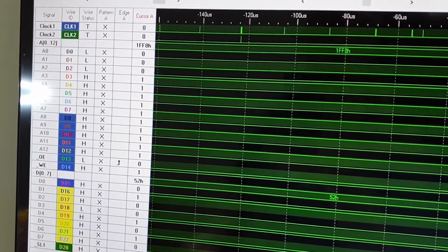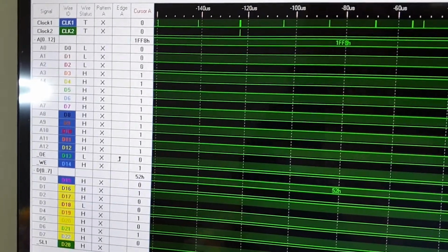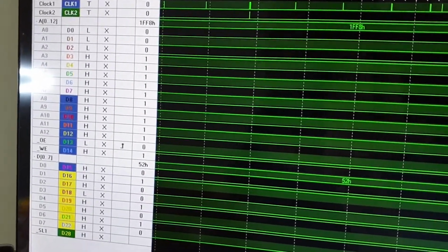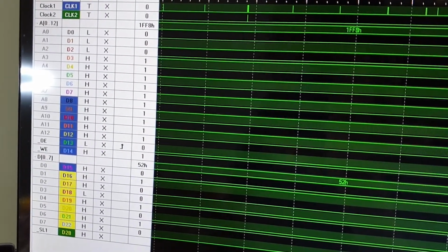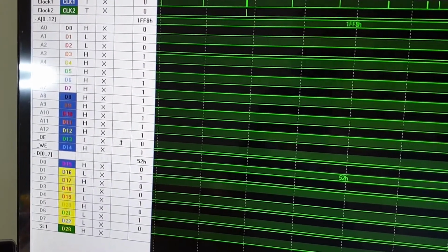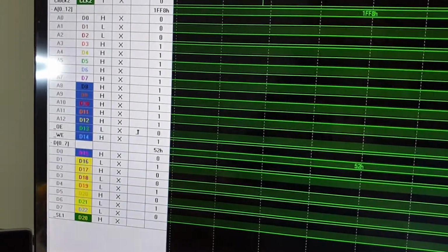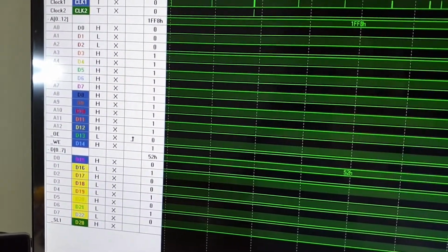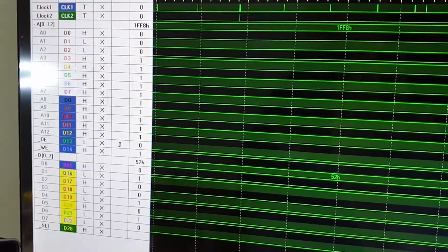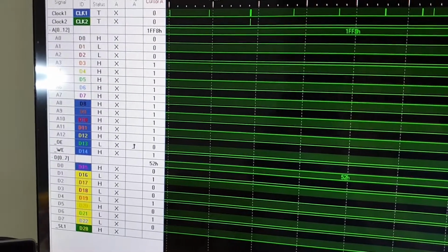It's proving that the memory address has been written to in the RAM, and now when it reads it back again, it's okay. But if I then change, say for example, the horizontal coordinate, which I think is now high, low, low, low, we can see here that the memory address contains whatever was in the memory at that particular point in time. The memory doesn't have a default. Of course, it's random-ish, slightly noisy data each time.